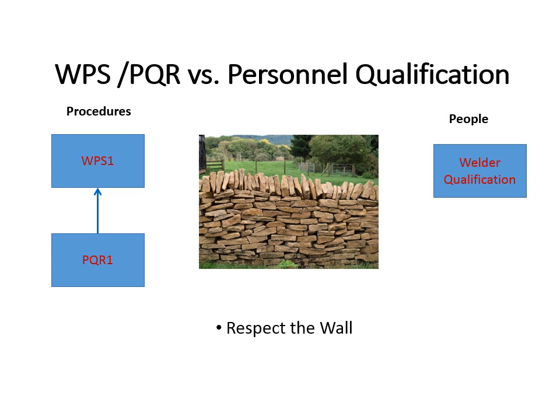There's a little overlap with a couple of the terminology, but don't mix and match people and procedure qualifications. Welder qualifications and WPSs and PQRs, they live in two different sides of the wall. You need to respect the wall and not crisscross things.